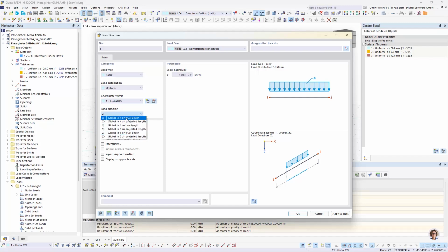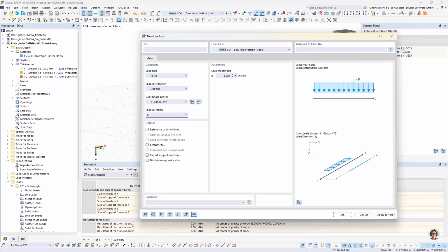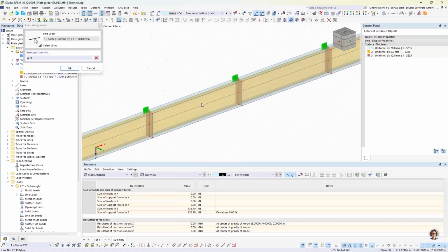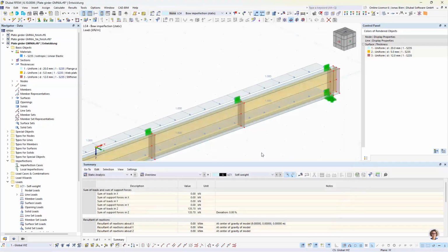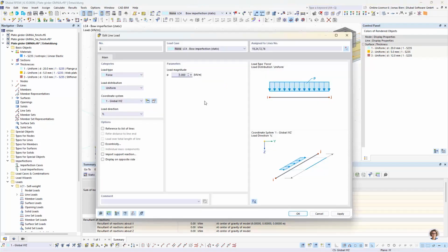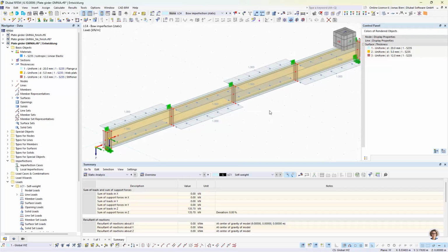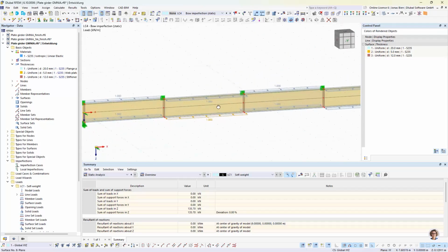So first of all, I want to deform my girder in y direction by defining loads on those lines between web and flange plates, so I avoid that my section itself deforms. I want more or less a member deformation without distortion of the cross section. So I just apply this, let's say, dummy load in one direction, and then I alternate the direction of the deformation.